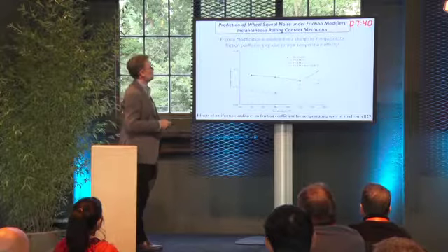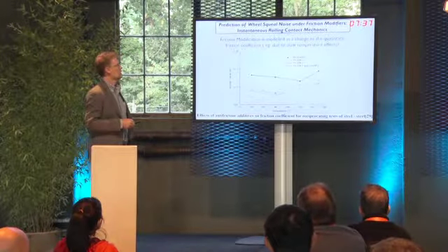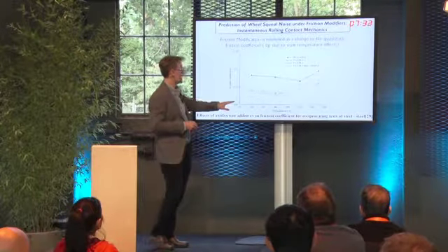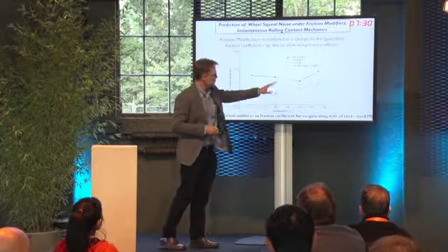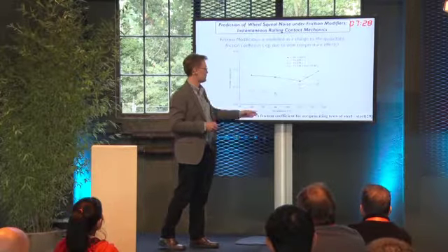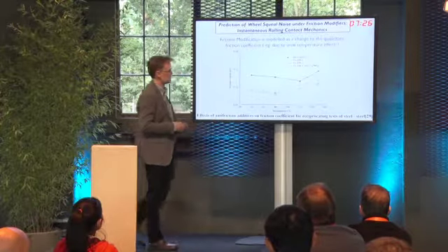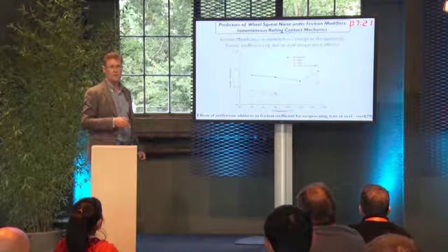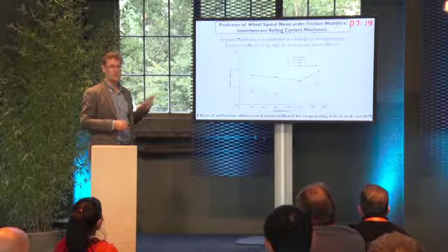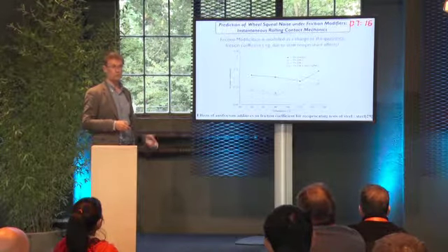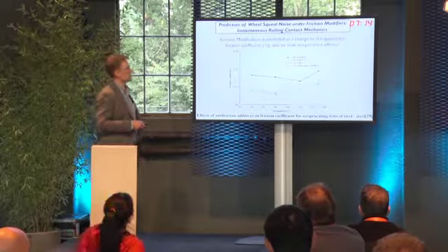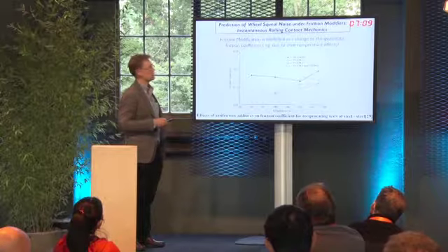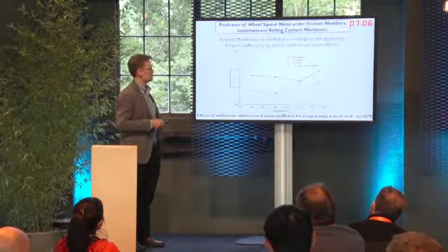In order to model the effect of friction modification, we looked at some of the theory and realised that the friction coefficient rises under friction modification due to an increase in temperature. But these temperature effects are expected to be slow compared to the oscillation of squeal, which is above 1,000 Hertz. So the time constant of the temperature dynamics will be much slower than the squeal itself.